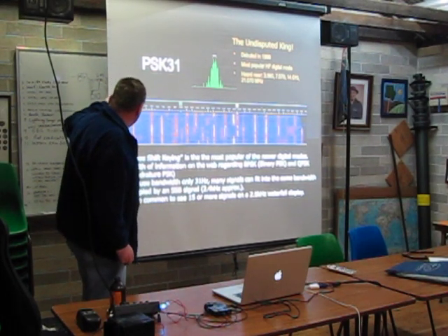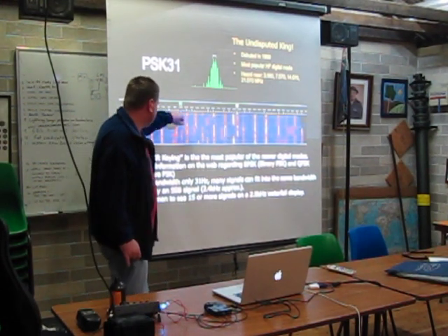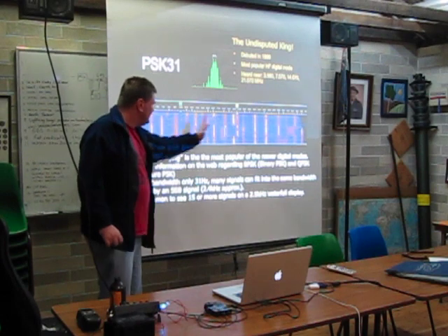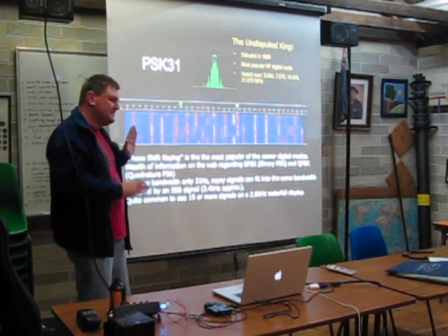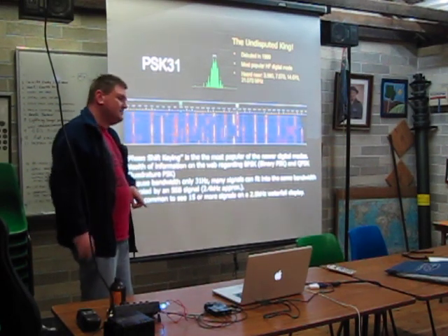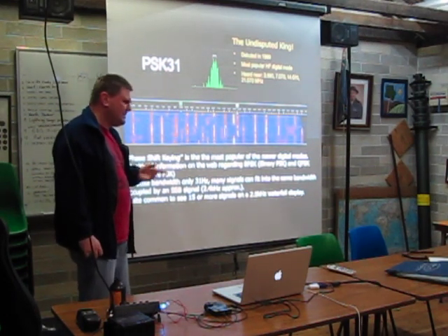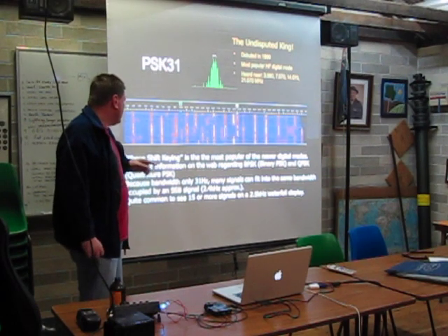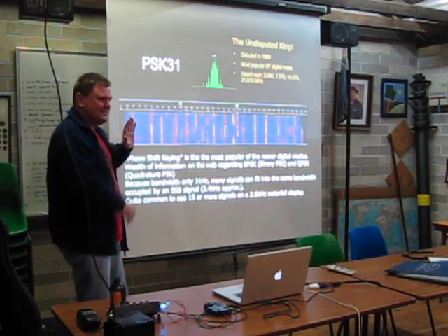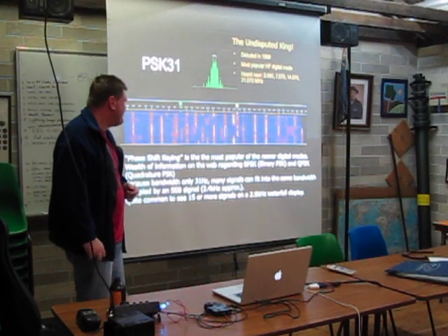So here you can see you've got the frequency along the top scale. Here we've got 200 hertz, there's 1000 hertz, a kilohertz, 2 kilohertz. And so you can have lots of these PSK signals being picked up by your receiver at once. With the computer you can click on one particular signal that you're interested in, and the computer will decode it. And I'll show you a program a bit later where the program can actually decode all the signals at the same time, and you can have a ticker tape, like in a stock exchange, of all the different conversations going on at once. So that's really quite interesting to see.